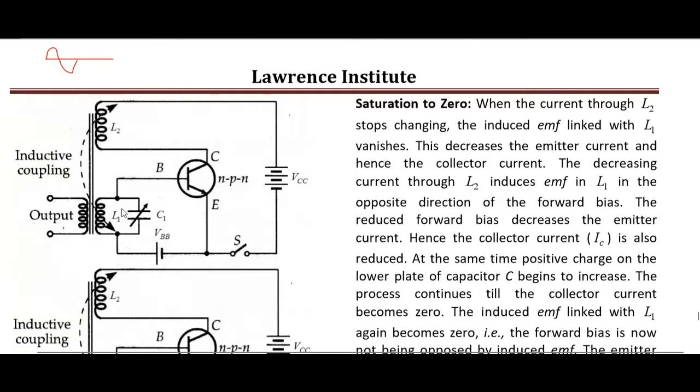And now when the current grows here, the inductor opposes the very growth of current. Now this opposition gets coupled with this, and this opposition is once more opposed. You can say the positive thing was made negative by this L2, and that negative was again made negative. Two negatives make one positive. So here this is an in-phase coupling. You can think in this way.